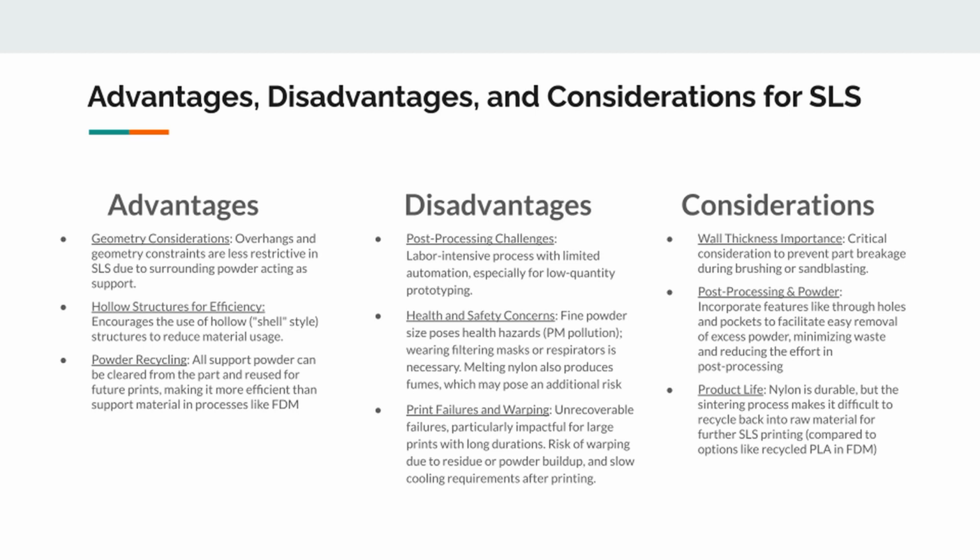Print failures and warping are also a big disadvantage because they're unrecoverable failures that require you to restart another print if they happen. The risk of warping is due to residue and powder buildup and slow cooling requirements after printing.